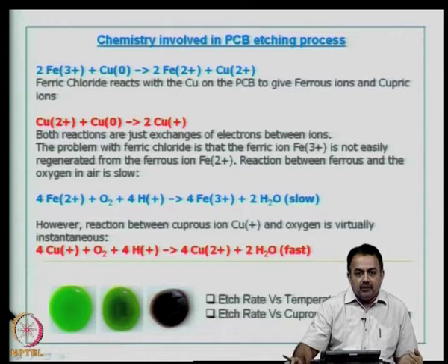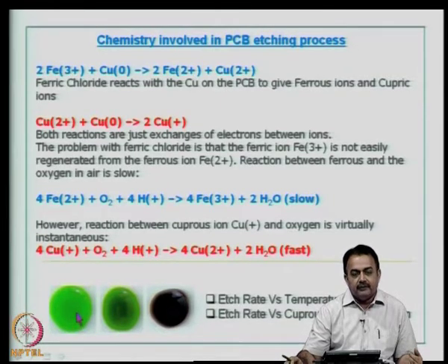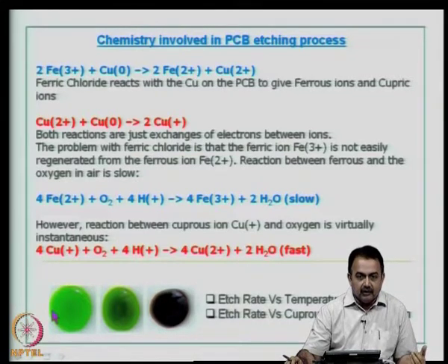Now, at the bottom what you see here is the progress observed, okay, in a cupric chloride etchant. For example, you see here at the extreme left, this is a very new solution of cupric chloride, which is mild green in color.